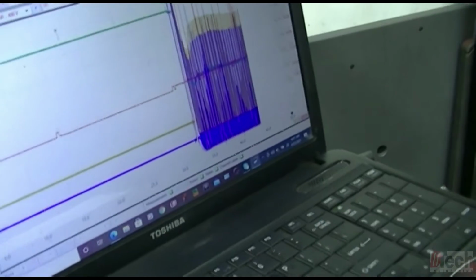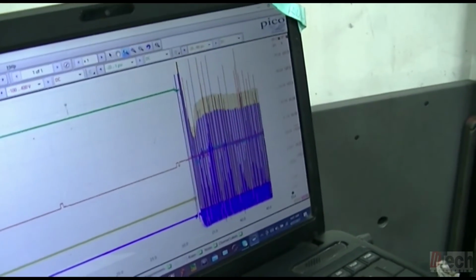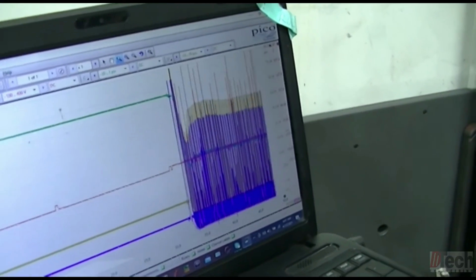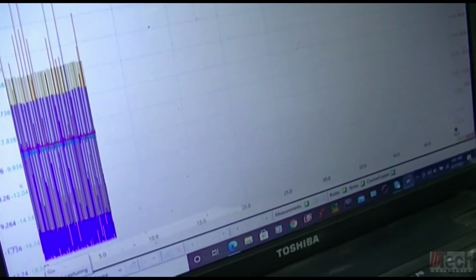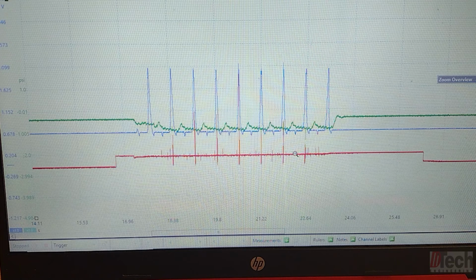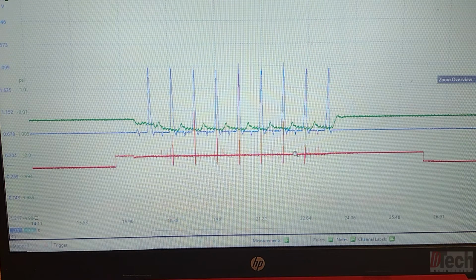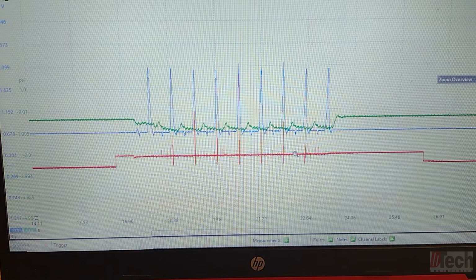Okay, so I'm running both cylinders number 1 and 8 to get a good look at what they are going to look like on the waveform for a first cold start pressure in cylinder. Off camera, I actually ended up doing a couple more tests along with the in-cylinder during running. I actually ended up doing some cranking tests. Again, this is just above and beyond. It's just for my curiosity, and so I wanted to show some of the things that I found on this.